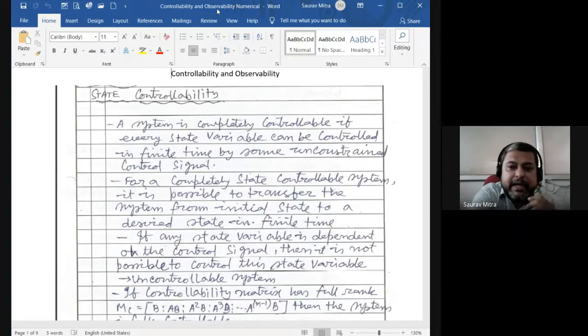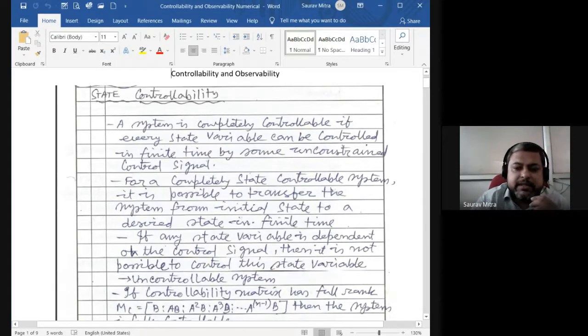To explain all the dynamics of a second order system, we have to define a maximum of two state variables. So for the second order RLC system, the state variables were inductive current and capacitive voltage. And we had seen the different state variable models for the RLC system. Now one thing we also have to define is the output variable. If we take the output variable as inductive current, the C matrix will be different. If we take the output variable as capacitive voltage, then the C matrix will be different. So the C matrix is called the output matrix, the A matrix is the system matrix, and the B matrix is called the input matrix.